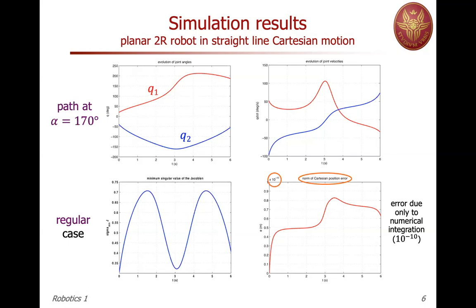At the midpoint, since we are getting closer to the origin, which is another situation of singularity, you see that there's a reduction again, and then the motion is almost symmetric. In fact, you end up with a final value at time equals 6 seconds, which is higher than the value that you had at the beginning, and also than the minimum at the center. Okay, so this is in order to check if we are getting close to a singularity.